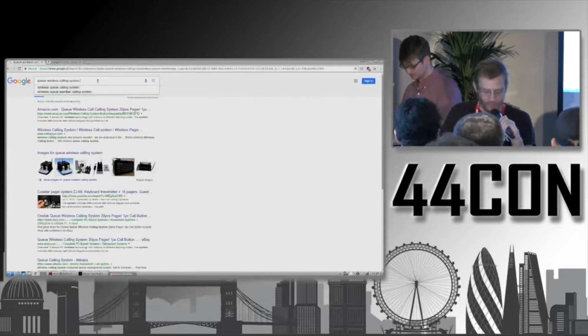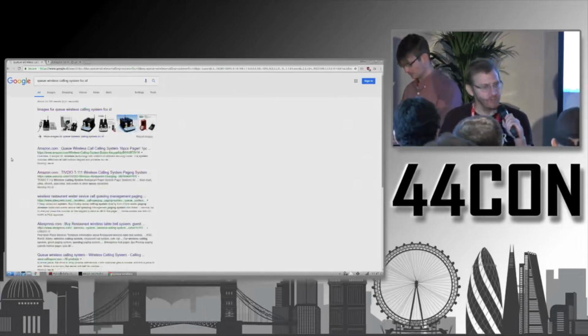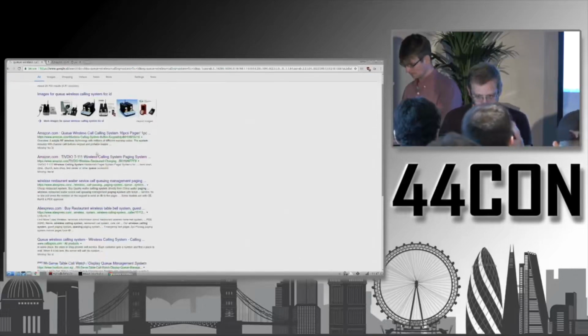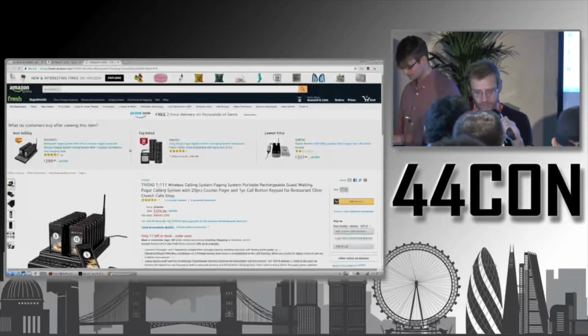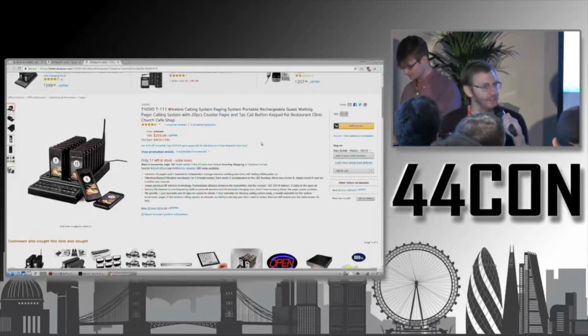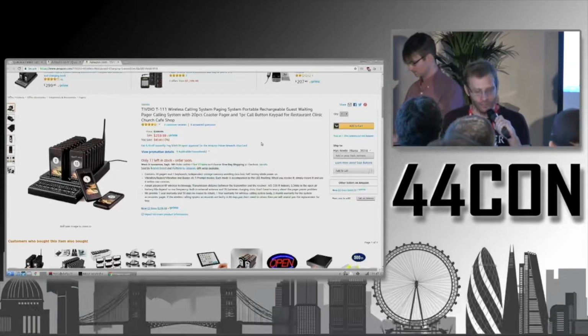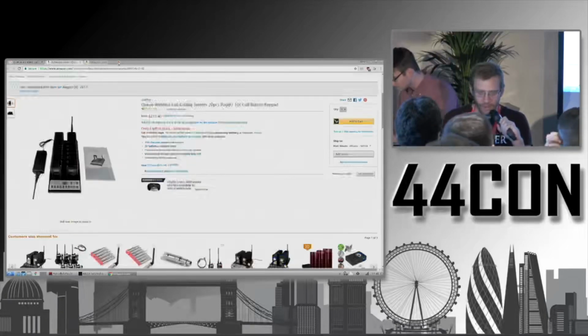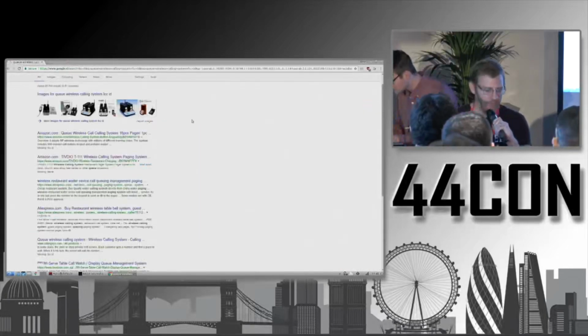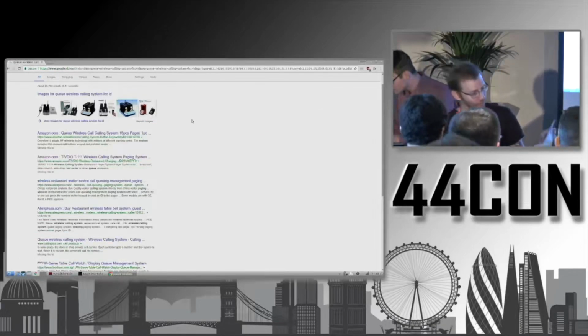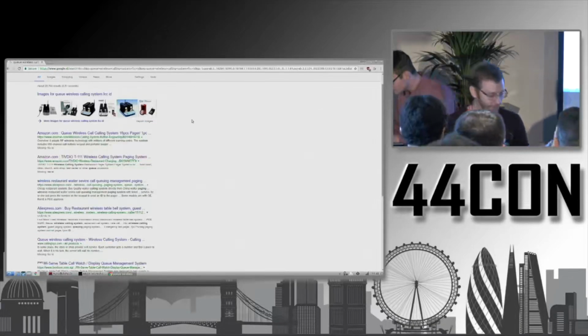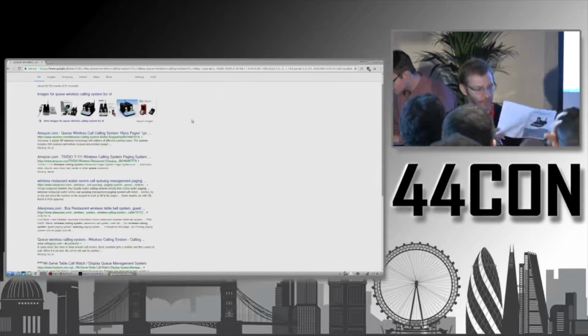So if we, for example, put in FCC ID, you can often find mentions of FCC IDs for products elsewhere. There was this other brand, it looks like, that has the same product. Unfortunately, no FCC ID for this one either. So this is a case where we just have some cheap Chinese product that really doesn't have any good documentation and no regulatory registration or certification. So that means that we're kind of stuck with this 433.92 megahertz figure from the user manual here, and we have to start looking at the spectrum to see what's actually going on.